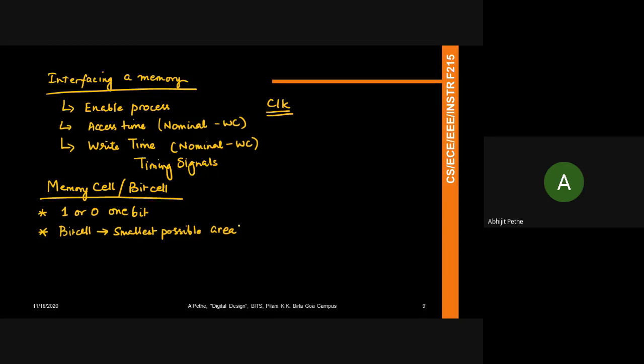So designing memory is important not only because it determines your area, it also determines your power consumption in the chip. The more you access the memory, the more power you're going to burn. Also, even if you're not accessing it, the memory will continue to leak current. All those things impact the total power curve of your chip. So you need to keep in mind that when you design a bit cell at the transistor level, it needs to have the lowest amount of leakage possible.